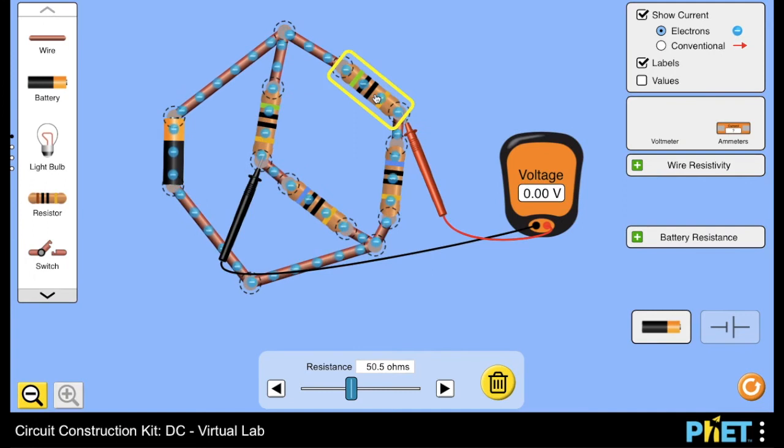In that case, after you acquire values for R3, R2 and R1, you can apply the equation that we have established previously, Rx equals R2 times R3 over R1, in order to theoretically find the value for Rx and then compare it to the experimental value that you obtain over here, which is 60.5 ohms. Initially during an experiment, that resistor Rx is going to be wrapped up. It's going to be covered with a tape in order to hide its resistance from you.